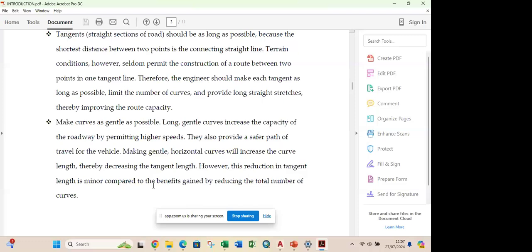So if I'm going below that, I'm going contrary to what I'm designing for. The radius is now lower compared to the minimum stated, which is 123. If I'm driving at the speed of 60 km per hour and I'm approaching that curve, I should be able to navigate that curve at 60 km per hour.